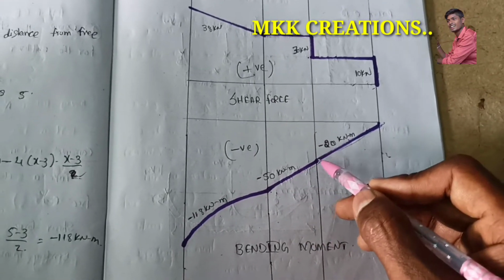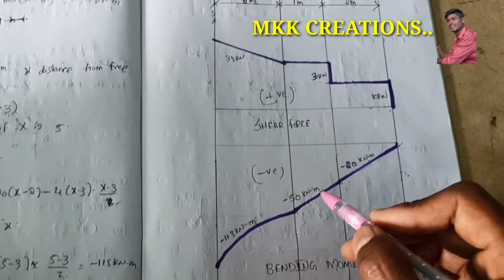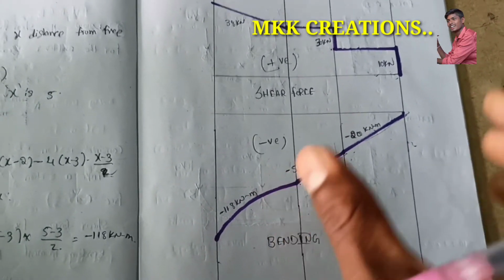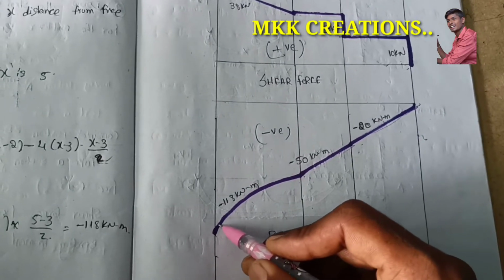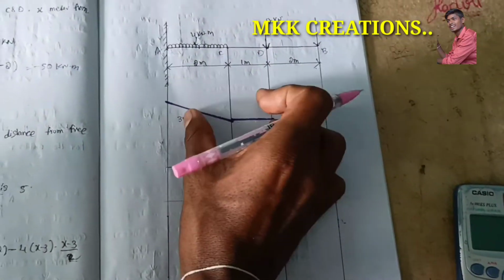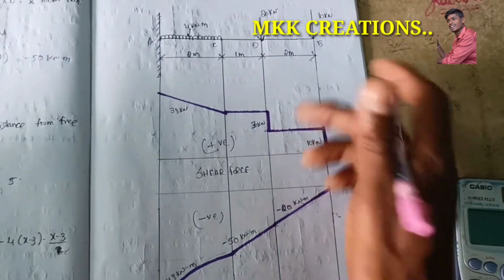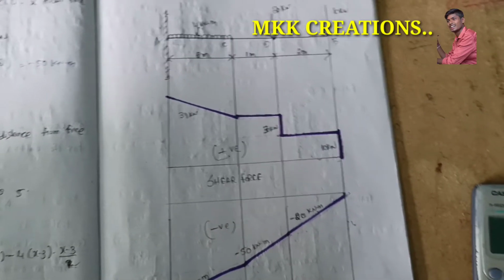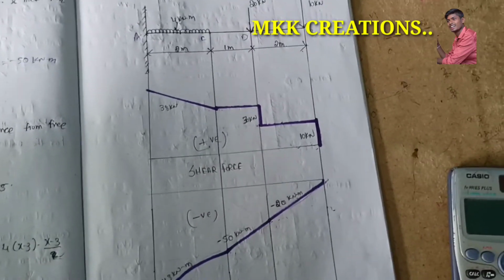Next at portion AC we have the uniformly distributed load, so we start the parabolic curve. For a point load we draw slanted lines. So this is the way of solving problems in shear force and bending moment diagrams.